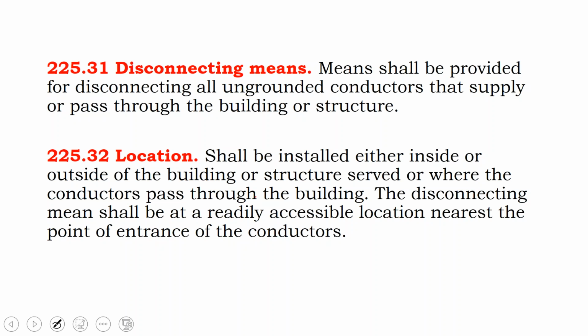So in short, with all these disconnects, the arrays need to have a disconnect switch. What the utility really wants is a disconnect switch that's outside of the home, that's readily accessible to them, that during an emergency, they can come and turn off power to the entire building. But that's going to get a little more complicated as solar and batteries come onto the scope, because now they'll be used not just for standby systems, but also for emergency systems.